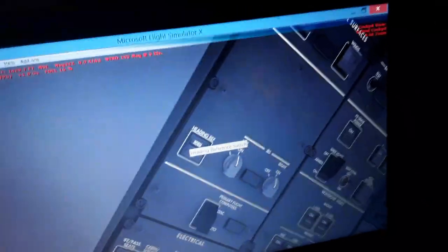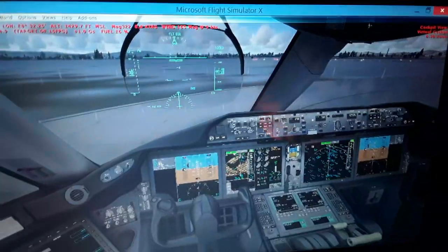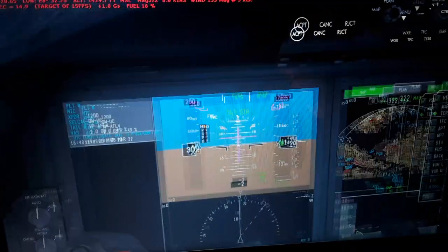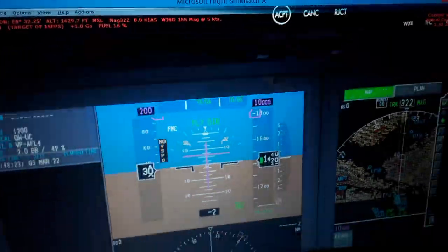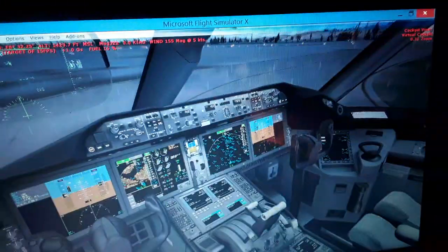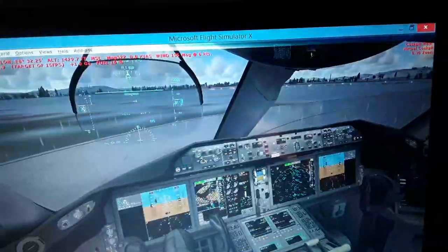The magnetic variation is displayed in the navigation display. This is controlled also from the air data computer, as well as the airspeed data. This also calculates the rate of climb and descent, the pitch angle of the aircraft, and the laser gyroscopes for the inertial acceleration and deceleration of the aircraft, and other data.